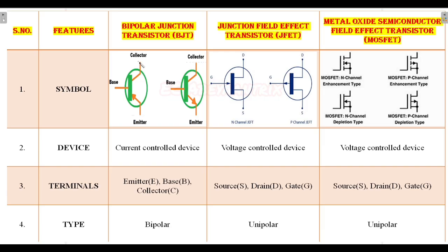As I said earlier, there are three terminals called emitter, base, and collector. I have mentioned emitter, base, collector in my BJT video too. Coming to doping, the emitter has the highest doping, and coming to size, the collector has the largest size among the three. So keep this point in mind, mainly for your exams. The same applies to the NPN transistor also. So in BJT, the emitter has the highest doping and the collector has the largest size, but the base current alone controls the entire device. Keep that point in mind also.